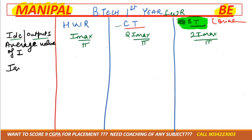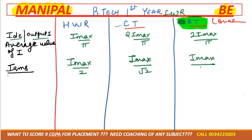Next, sometimes they'll ask you IRMS. IRMS means the root mean square current. For half wave the formula is Imax by 2. For center tap it is Imax by root 2. Again for the full wave it is common, basically Imax by root 2.